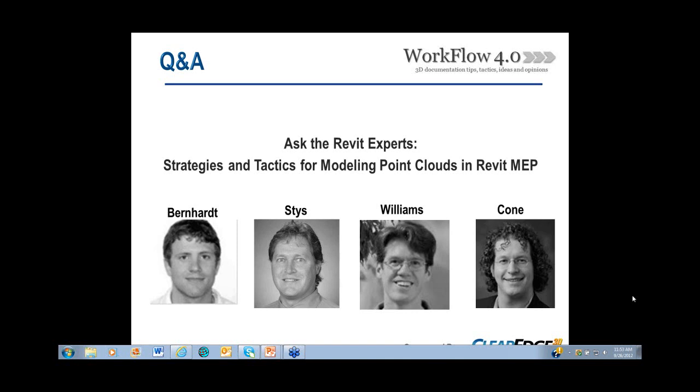Okay. And Kevin, do pipes always import into Revit as PVC? Why not a generic pipe family? So the placeholders, I'm not a Revit expert, and I actually have fairly limited time in front of Revit. So Kyle, correct me if I'm wrong here, but placeholders essentially do that. The pipes that we export as pipes and elbows right now come in by default as PVC, but they can be changed. But that is just that much more flexible if they come in as placeholders. So you can change them to whatever library or family you have available.